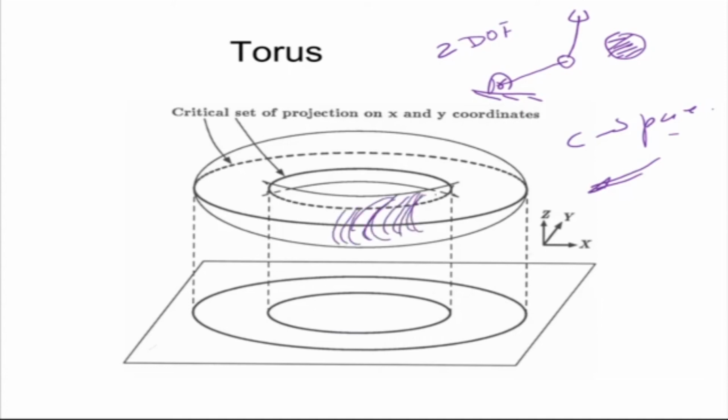of the torus now. Now I want to do path planning on this torus. Please note that the torus is 2D basically. The torus has two variables, theta 1 and theta 2. But when you draw it, you require x, y, and z in terms of dimensions. So now if you want to do path planning, let's say this is my obstacle. I want to do path planning on the torus now. Now how do you do path planning on the torus?